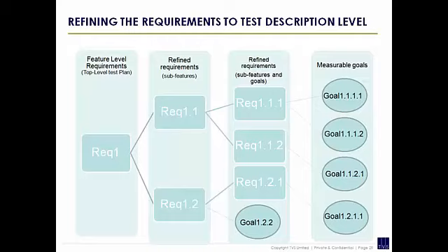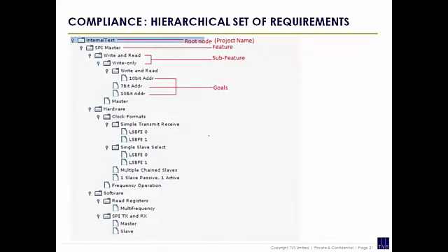rather than just traditional directed tests. And we can map these also to code coverage. So you may be mapping it to MCDC. So you may, on a particular unit, want 100% MCDC to sign off that requirement. Okay, so you can map it to structural coverages as well as functional coverage, as well as assertions, as well as formal proof, as well as directed tests. Okay. So here's an example.